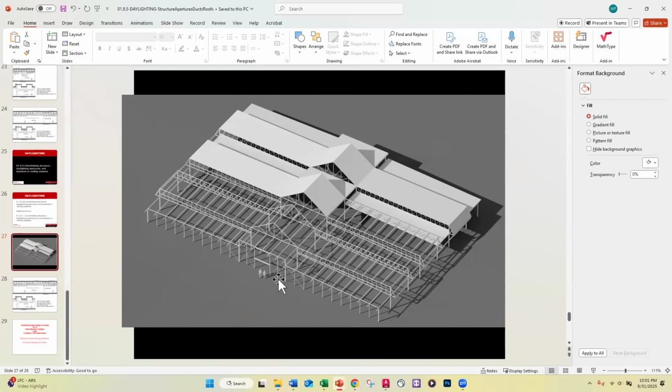There's no ductwork. So as we discussed the need for ductwork, we said, let's run some trunk lines in this spine, and then those trunk lines could inject air through this space and out to the boundary of the space.